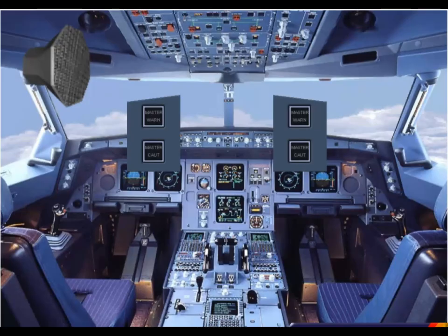When the fault occurs, the ECAM system alerts the crew orally and visually. You hear a continuous repetitive chime and see the master warning lights flashing. Press one of the master warning push buttons to cancel the master warning lights, stop the chimes, and reset the alerting system.